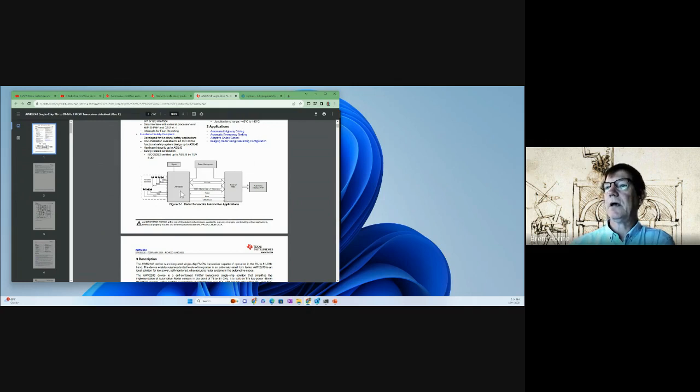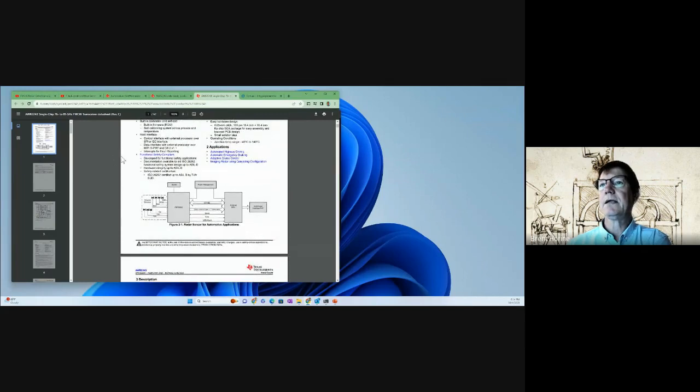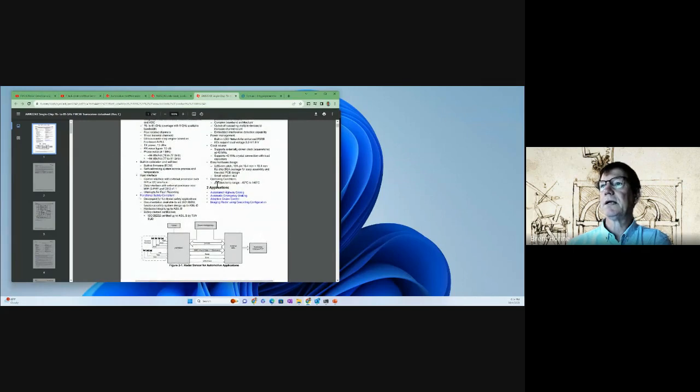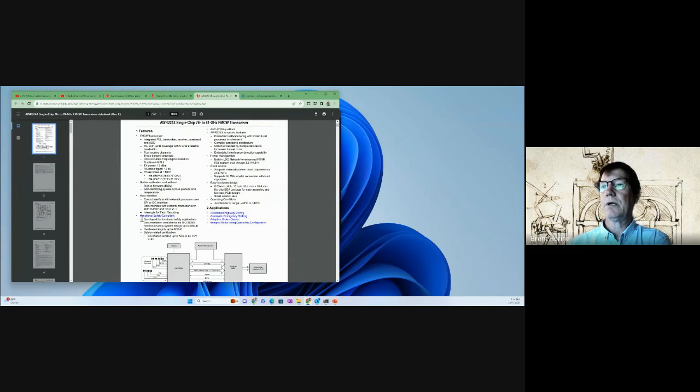But then this is your RF chip, but it's connected to this external microcontroller, and that's doing all those calculations, FFTs and peak searches, and actually going through those equations. And then all that information goes out over some automotive interface. Is that a CAN bus or something? I don't know on this particular one here. So might be a higher speed than CAN.